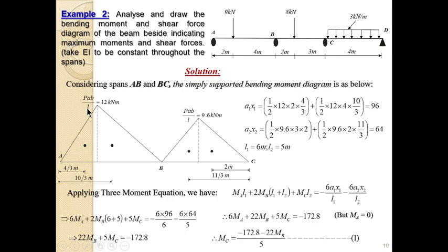It might do you some favor to take note of all these formulas, they help. So PAB means 9 times 2 times 4, divided by L, and L is 6, so that gives us 12 kilonewton meter. And the same thing here, PAB over L. In this span, the load is not at mid-span, so you do PAB over L, and it gives us 9.6 kilonewton meter.